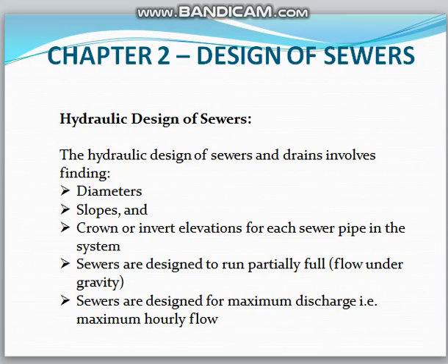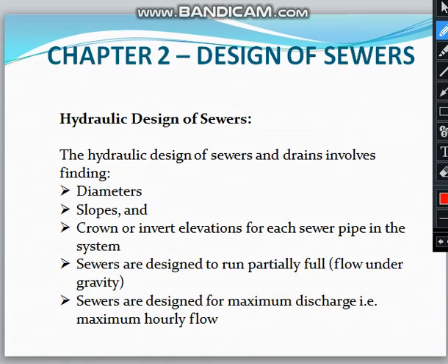Design of sewers. The hydraulic design of sewers and drains involves finding the diameter, slope, crown or invert elevations for each sewer pipe in the system. Generally, these three things are very important: the diameter, slope, crown or invert elevations.